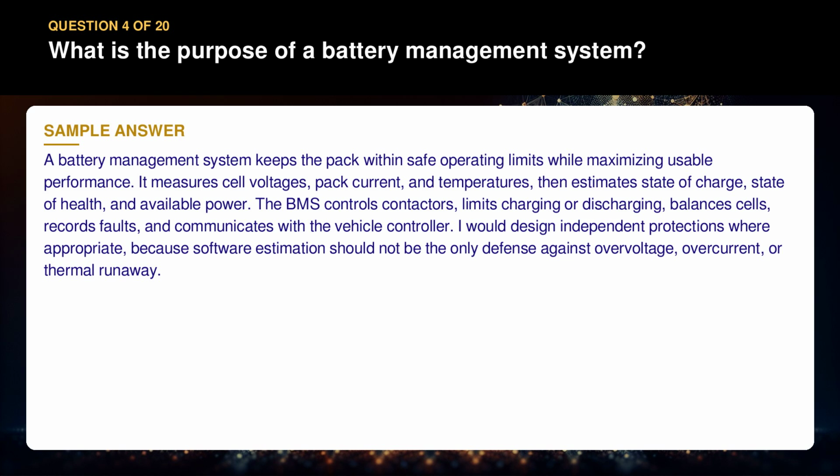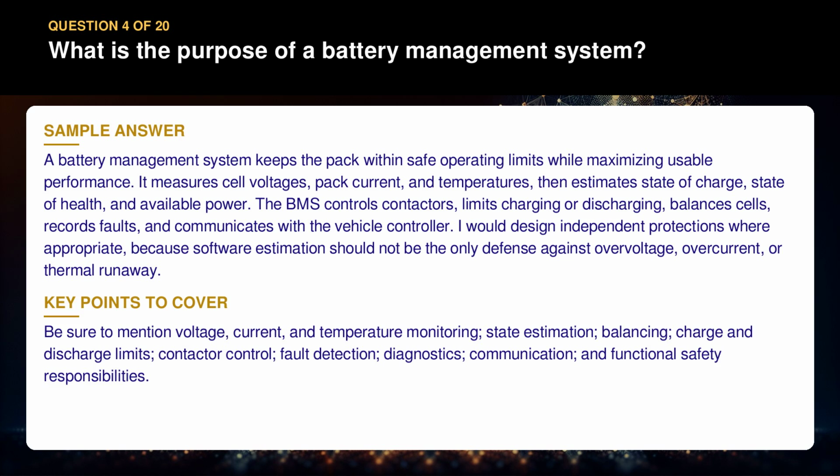I would design independent protections where appropriate, because software estimation should not be the only defense against overvoltage, overcurrent, or thermal runaway. Be sure to mention voltage, current, and temperature monitoring, state estimation, balancing, charge and discharge limits, contactor control, fault detection, diagnostics, communication, and functional safety responsibilities.